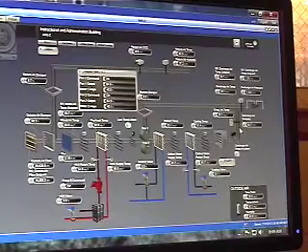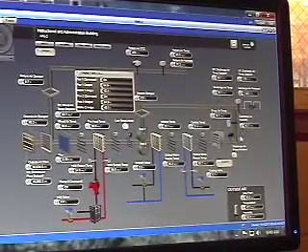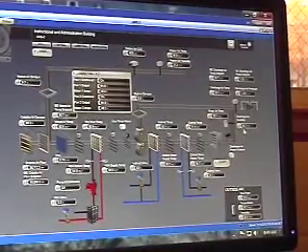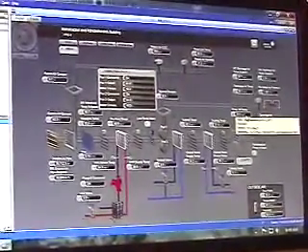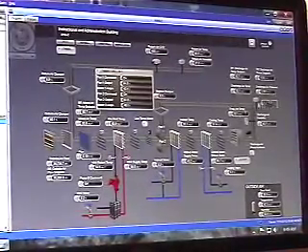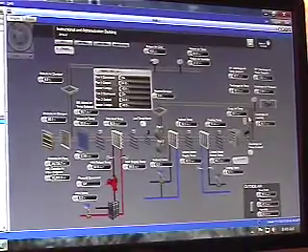Going up, discharge air humidity. This is a sensor that's not used for control, it's just for monitoring purposes. Please note that when you're running an evap media, that can be a very high number. Don't get too concerned about it, but the colder and more humid the air, the higher it goes. Evaporative air temperature, that's right here. I guess a good point, this right here is just a monitoring sensor, it just lets you know what's coming out from the evap media.